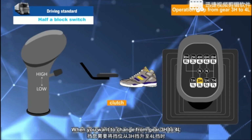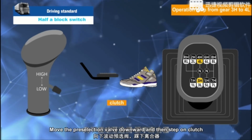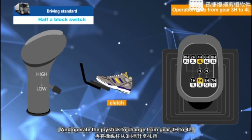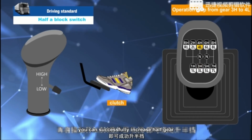When you want to change from gear 3H to 4L, move the pre-selection valve downward and then step on the clutch, and operate a joystick to change from gear 3H to 4L. You can successfully increase half gear.